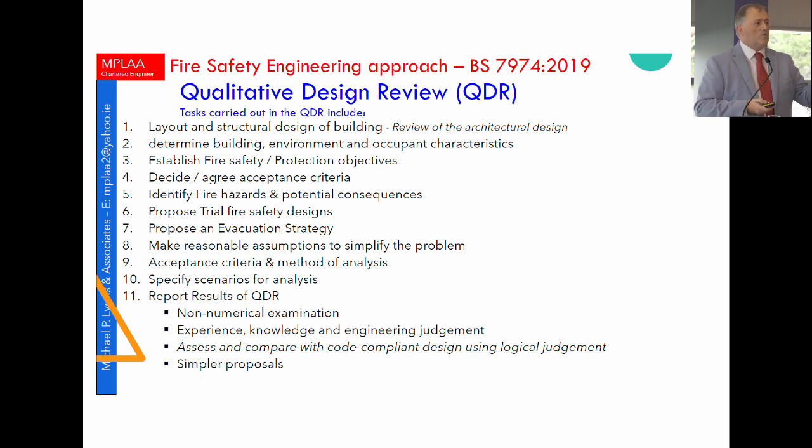of the year. You've got to be able to establish that your evacuation strategy for that design and a performance-based design does actually work. TGDB doesn't make any difference between Halloween, summer holidays, Christmas. It makes no difference whatsoever. TGDB is one design for everybody. But in a performance-based design, you've got to prove it.